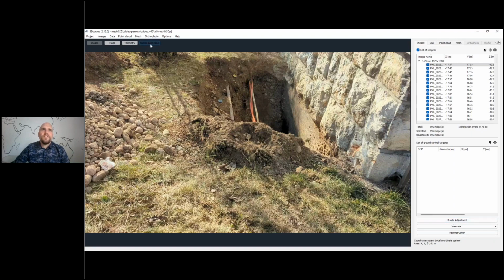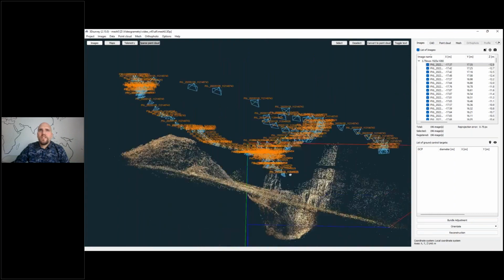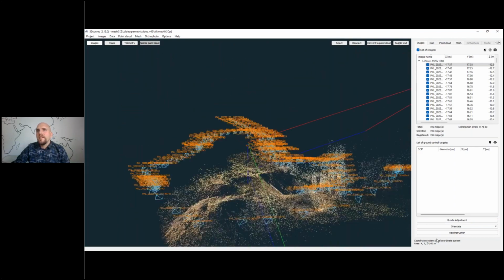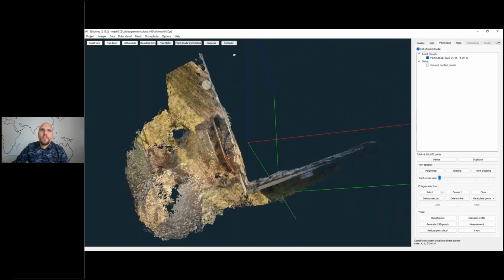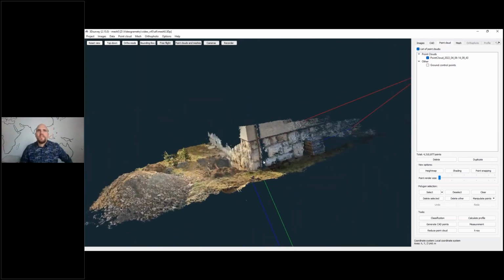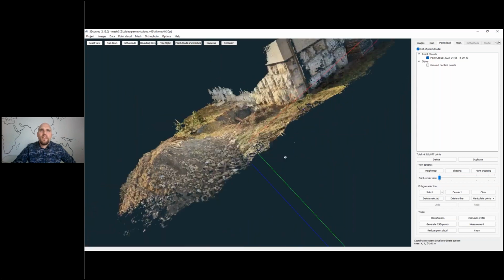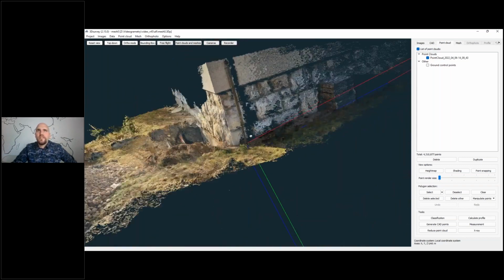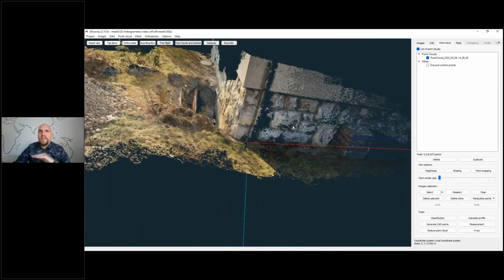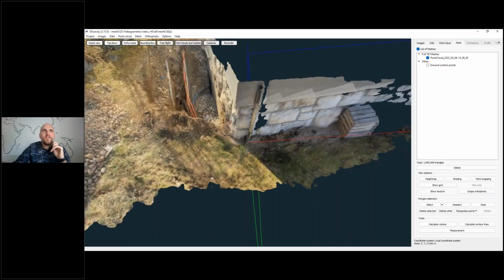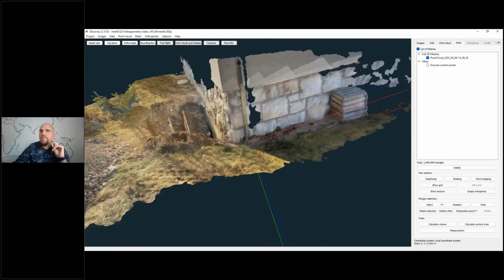After I got the results of bundle adjustment, I got a sparse cloud that is not orientated. Then I went from this point straight into reconstruction, on high, which only took about 15 minutes or so. After that, we got this point cloud. Again, because we haven't provided any georeferencing yet, the data is not georeferenced, nor is it scaled or correctly orientated. Then on the unoriented point cloud, I also created a mesh. This is the textured mesh for this area.